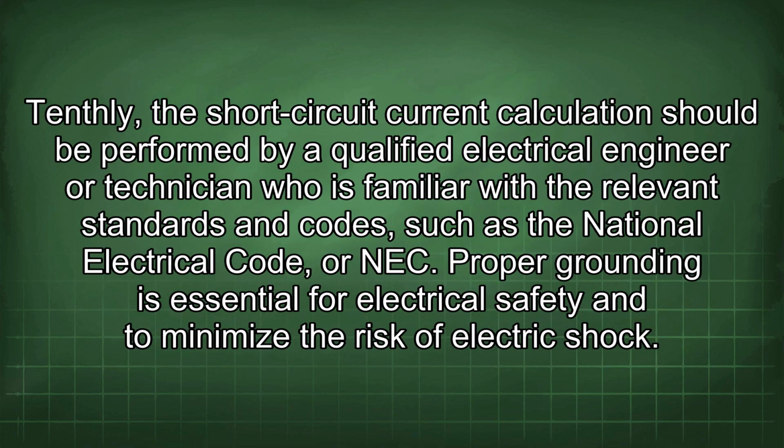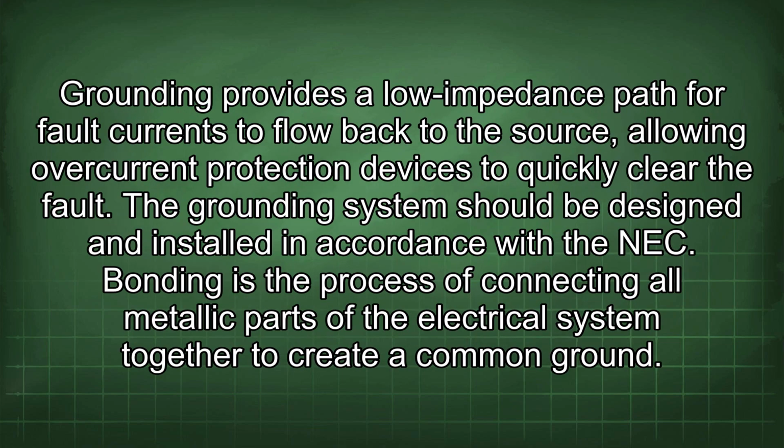Tenthly, this short-circuit current calculation should be performed by a qualified electrical engineer or technician who is familiar with the relevant standards and codes, such as the National Electrical Code, or NEC. Proper grounding is essential for electrical safety and to minimize the risk of electric shock. Grounding provides a low impedance path for fault currents to flow back to the source, allowing overcurrent protection devices to quickly clear the fault. The grounding system should be designed and installed in accordance with the NEC.